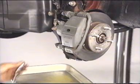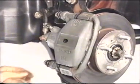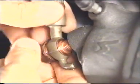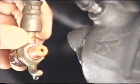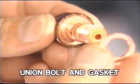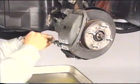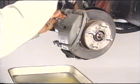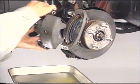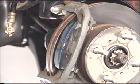Now, let's go on to the front disc brake wheel cylinder procedures. Remove the union bolt and the two gaskets from the brake cylinder. Prepare a container to collect brake fluid and remove the flexible hose. Grasp the sliding pin and remove the fixing bolt and cylinder from the torque plate. Remove the two brake pads.